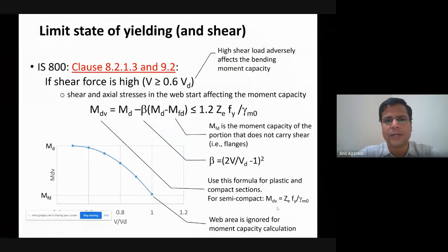So it is Fy by root 3 at which, at that stress level, the material yields. Now, if you imagine, for yielding under pure tension or pure compression, you need Fy stress. But under pure shear, you need only Fy by root 3 stress, right?